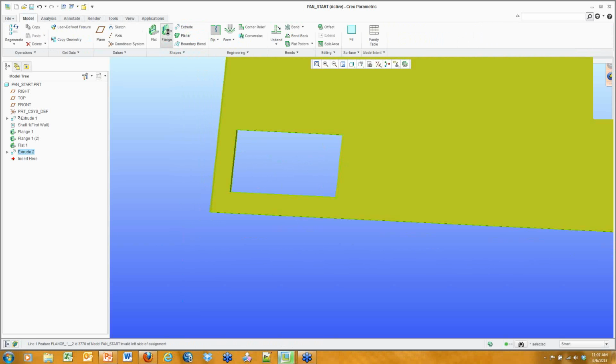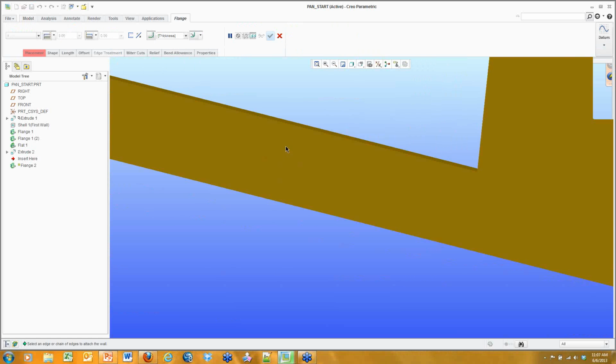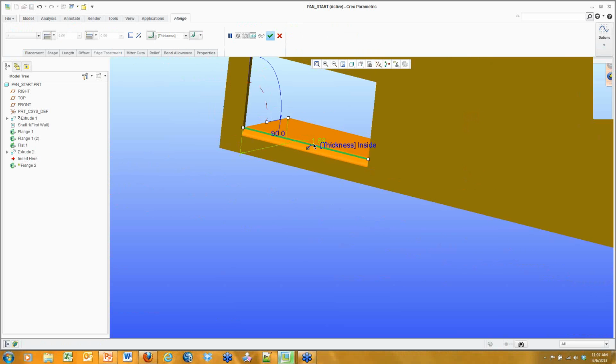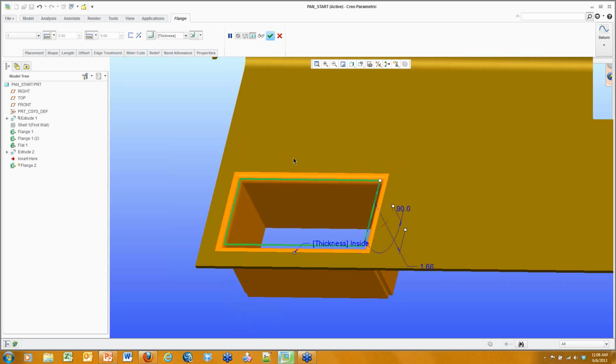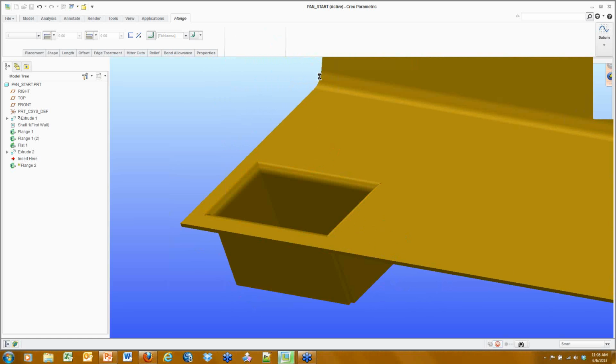Now, when we add a flange wall, I'm simply going to select one edge. Okay. Let's actually select this edge here. Now, if I want to select all 4 of these, yes, I can go around here and press Shift and select all of them, or I can press Shift and select, now watch this, see, I'm on this surface here. Notice the perimeter highlights green. Okay, left click, and it will automatically create your entire extrusion. Now I'm going to complete this.